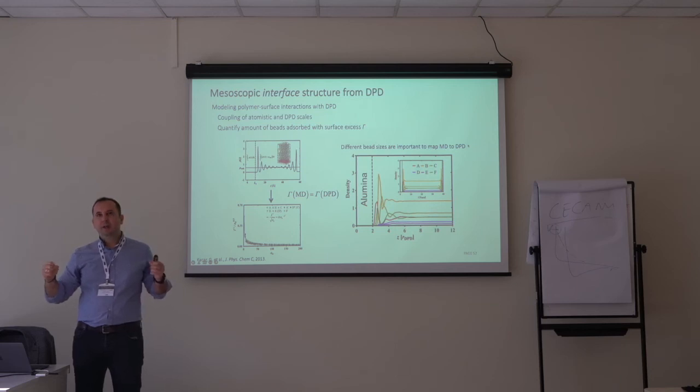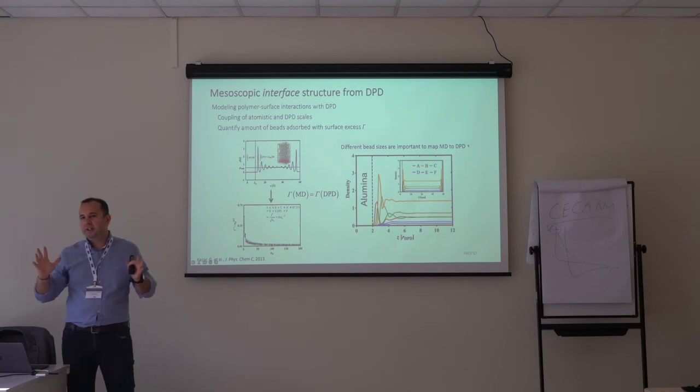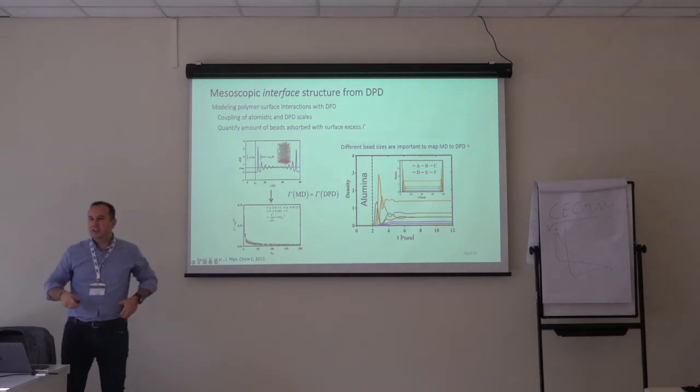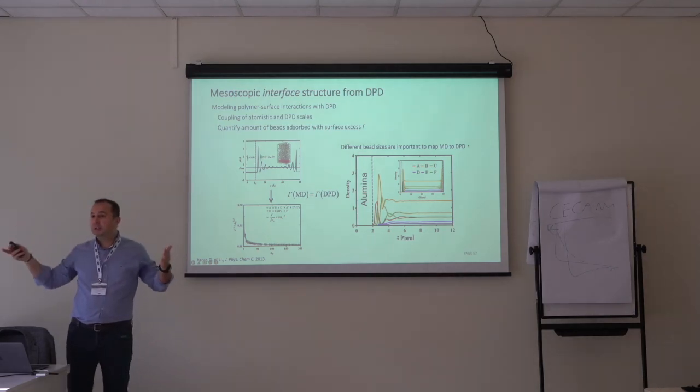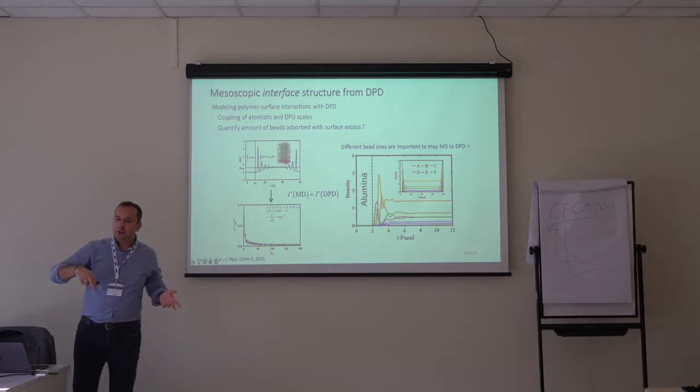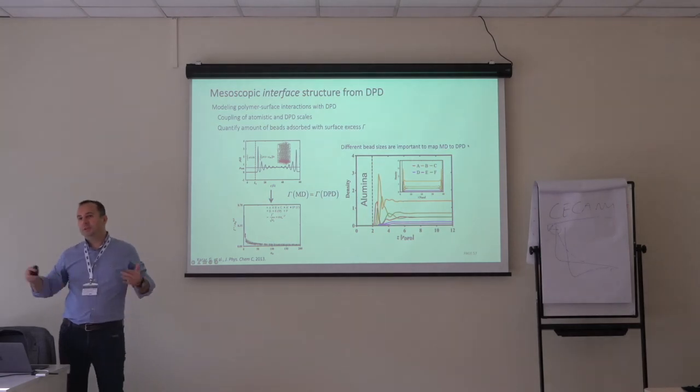You can imagine that you have a volume and you put a certain number of particles inside and then you increase the interactions between these particles. At the end, all particles will push each other and behave like a solid. So this is the same idea. You just increase the density, which leads to increased DPD repulsions, and then you can model the solid surface like this.